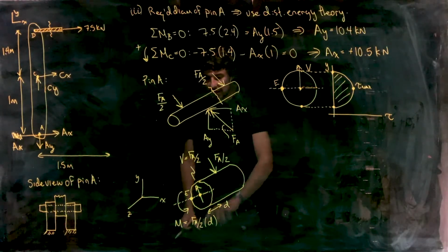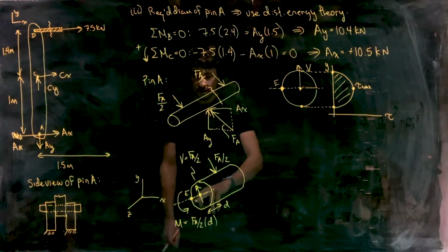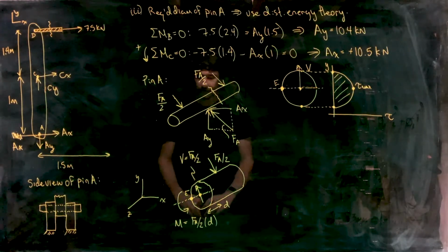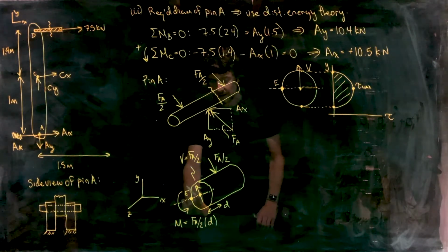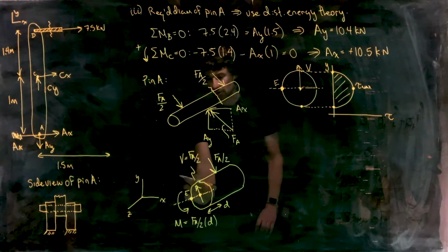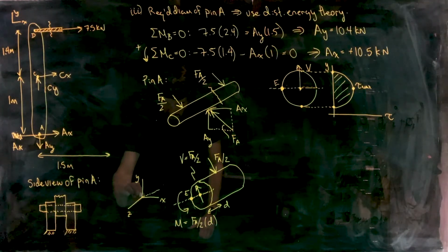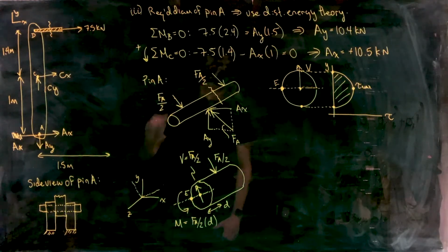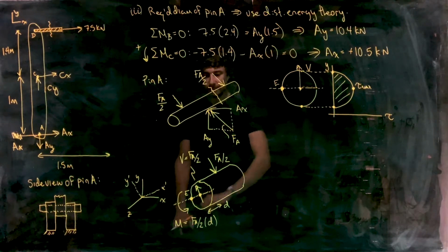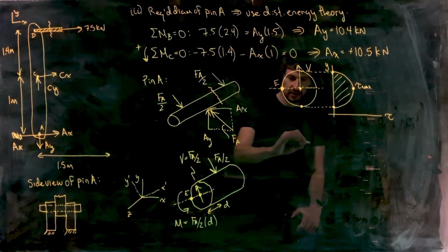So now we're looking at this face here in the XY plane up here. And let's draw our element of material that's located at point E. Because our shear is acting about an axis that's rotated relative to the XY plane, let's actually rotate this axis here and there. Now we've got a rotated x prime, y prime axis that is in the direction that makes sense for that point there. So let's draw our three-dimensional volumetric element at point E here.